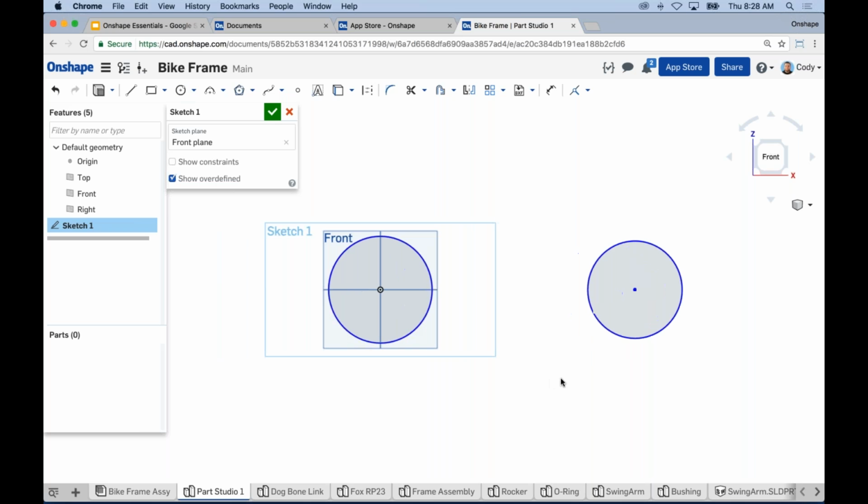So now I have two circles in my sketch, and I want to define the size of these two circles. Right now I have no idea what the size of them are. So I'll select the dimension command from the toolbar, left-click the first circle, left-click to place the dimension, and then enter a value, in this case 25. So 25, enter. Now, as soon as I do that, notice two things. First off, the entire sketch scales to match that first dimension, so everything shrinks.